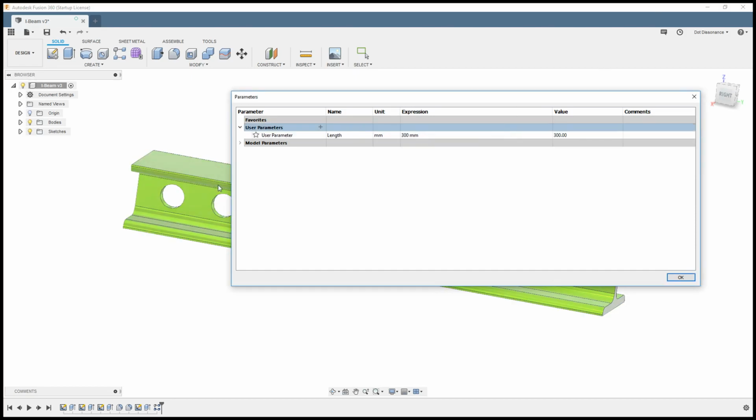Okay, nothing changed, just a parameter called length. Now the thing that you have to remember to do here is, just because we thought it really hard doesn't mean that the length of this part is going to change, because we just specified a name called length. We could call this banana or rutabaga or whatever we want in here, and nothing's going to happen. It's not like it's keying in off of the word length.